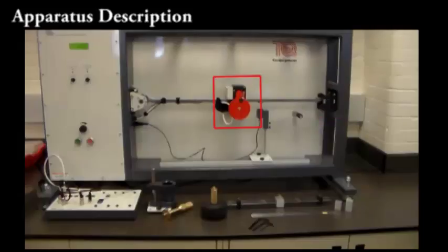A motor fixed to the beam has 2 rotating discs, each of which with an eccentric rotating mass. This combination forms an exciter, providing the forced vibrations. The exciter has sensors to measure motor speed and rotational position of the eccentric mass. This non-contact sensor measures the beam displacement by detecting the distance from a powerful magnet under the beam. This gives a measurement of the beam displacement at this position.